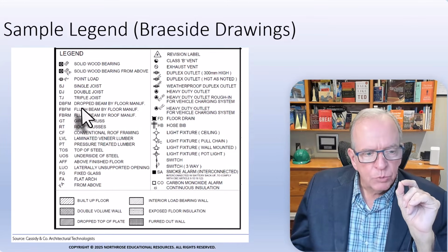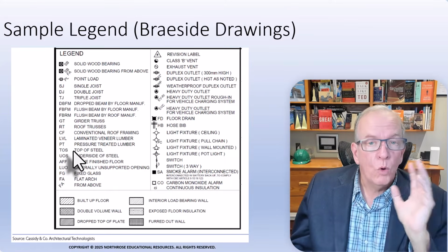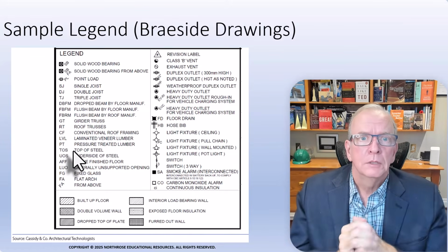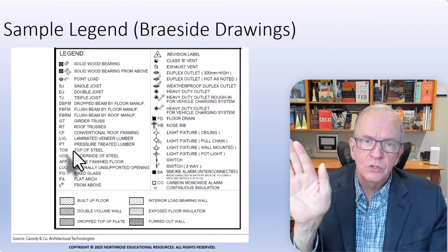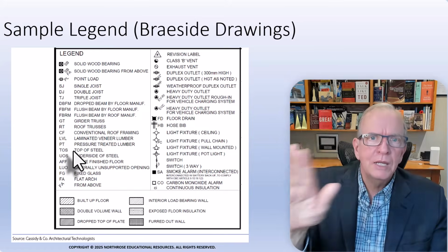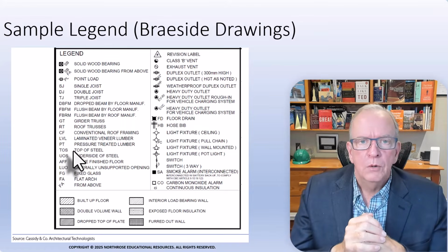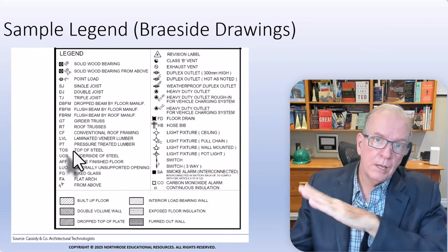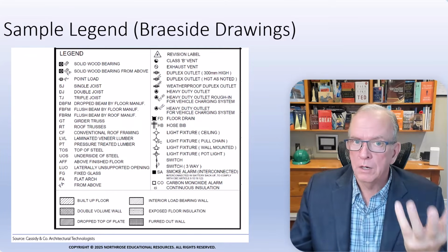That's what you also have to be careful about with abbreviations: one abbreviation could mean 4 or 5 different things. Like R. R could be showing you a radius of a circle. If you do concrete sidewalks and things, that could be the radius for the curb, you know, if you're into roads. And it might have an arrow and say 3 feet. Okay, I know that the radius of the curve of the sidewalk is 3 feet, R.